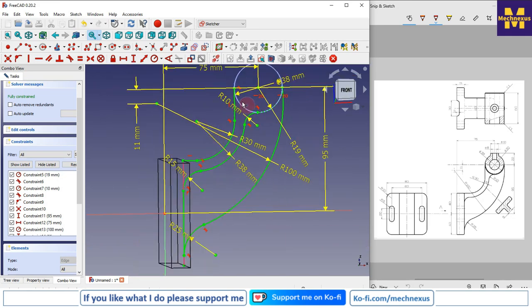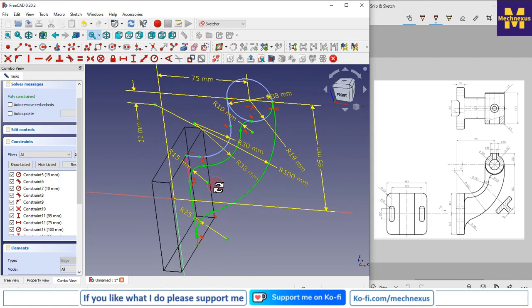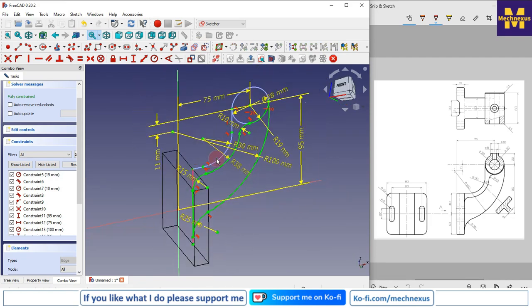Now we would make it constrained, because that would not be part of our extrusion. So I will select this and this, and make it construction. Okay, so this is how we have created our profile.